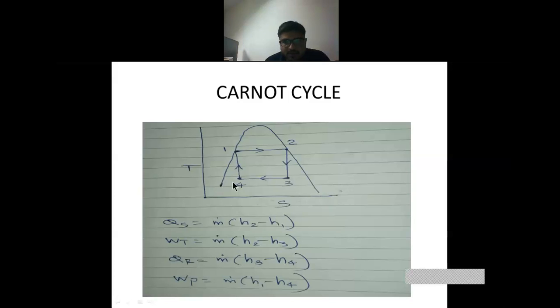Now which are the problems that we discussed? Here we can see that we are not completely converting the steam into water. Clear? So a problem may arise during pumping. In pumping we have a mixture of water and steam. It is very difficult to send it from the condenser to the boiler, because it is a mixture, and at that time it may separate. Clear? So in place of a pump, you may have to use a compressor.